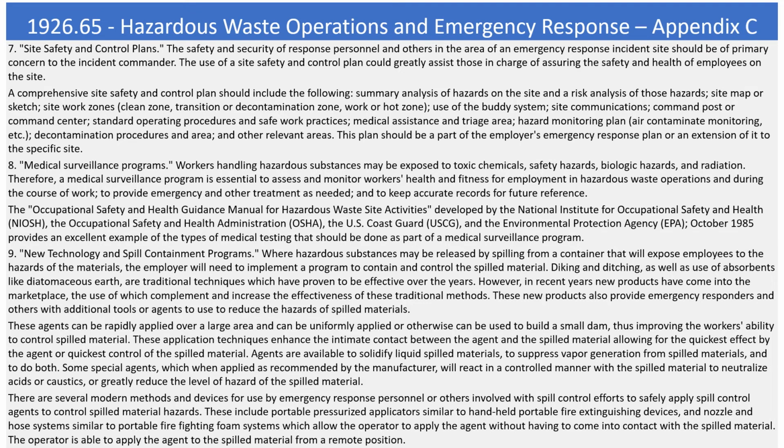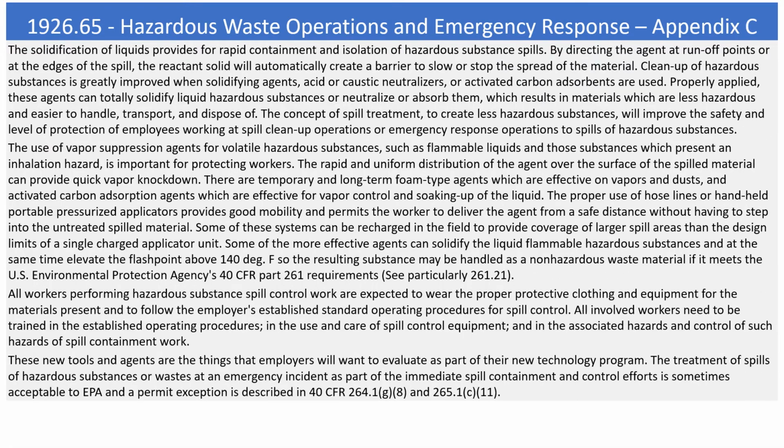These include portable pressurized applicators similar to handheld portable fire extinguishing devices, and nozzle and hose systems similar to portable fire-fighting foam systems, which allow the operator to apply the agent without having to come into contact with the spilled material. The operator is able to apply the agent to the spilled material from a remote position. The solidification of liquids provides for rapid containment and isolation of hazardous substance spills. By directing the agent at runoff points or at the edges of the spill, the reactant solid will automatically create a barrier to slow or stop the spread of the material.